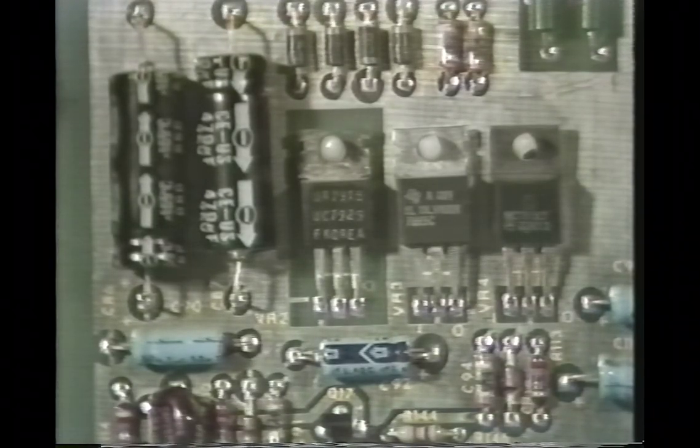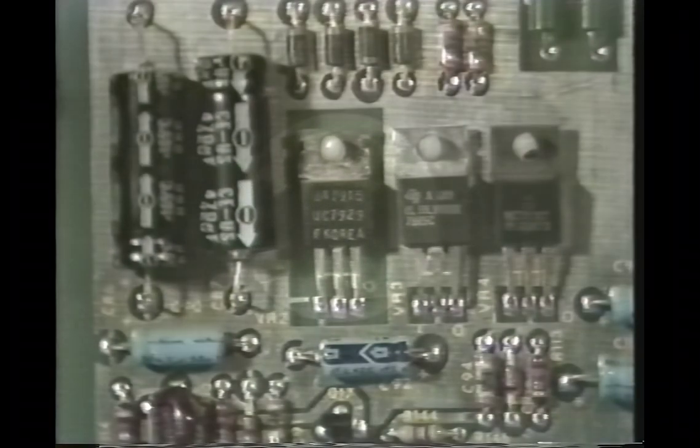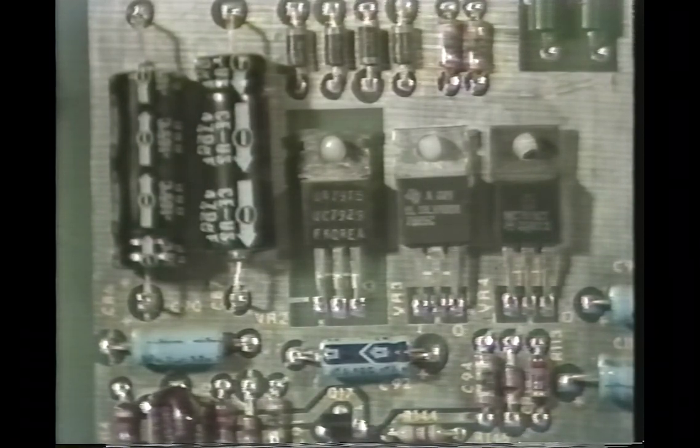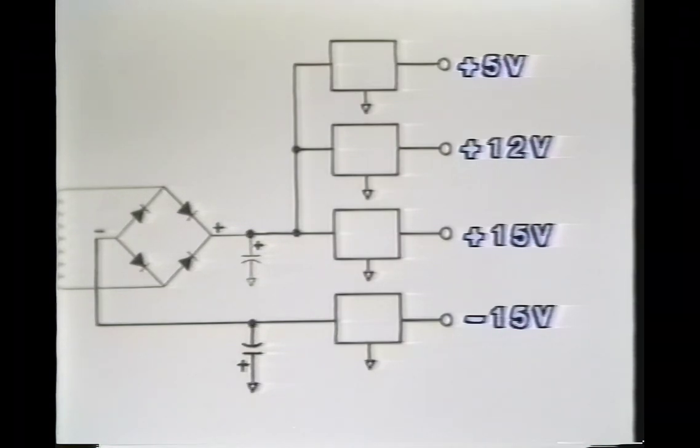This is a negative voltage regulator on Atari's Asteroids printed circuit board. Because the tab of the regulator is also the input, the grounded metal backing has been cut away from behind this regulator. By using a split supply and 4 voltage regulators, we can create 4 separate regulated power supplies.